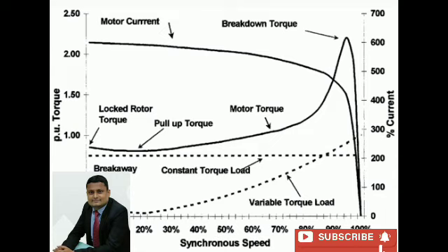Core loss in stator teeth. Flux density at a stator tooth. Calculate the flux density at 1 by third height of the stator tooth from its root. Then calculate the area of cross section of a stator tooth at 1 by third height from the root. So we need the width of the tooth at 1 by third height and the iron length of the core.